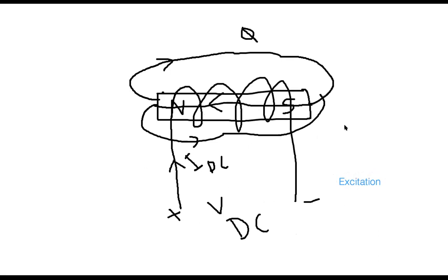And this is very, very important. Soon, probably in the next class or another class, we will be looking at how, depending on how much DC current you apply, power factor can be leading, lagging, or unity. This excitation has a huge role in power factor control. Pretty interesting. So that's why we are looking at the excitation system. Now, given this, let me go back there and then I will release you for today.